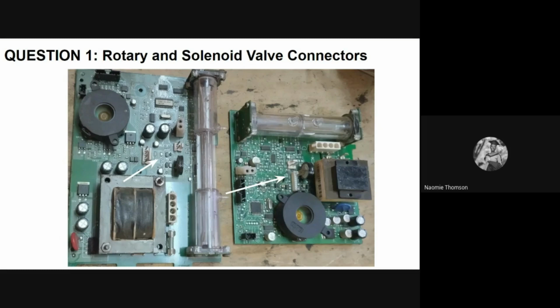So that means if you want to replace the solenoid valve block with the rotary valve block, you have to replace even the control board for it to function properly. The functionality is the same, but they just differ on the connector on the control board.